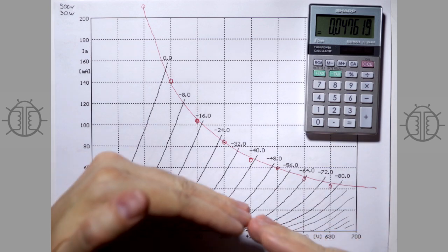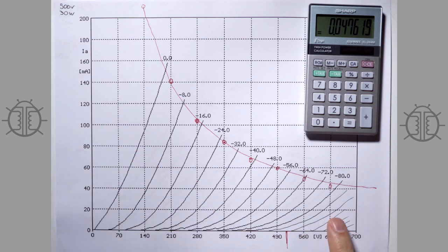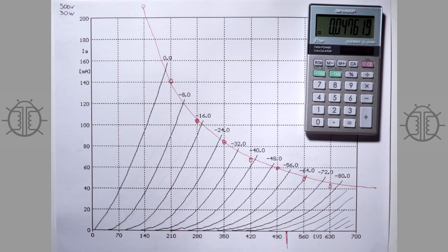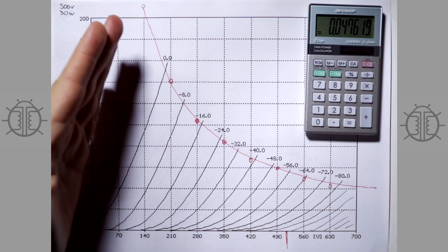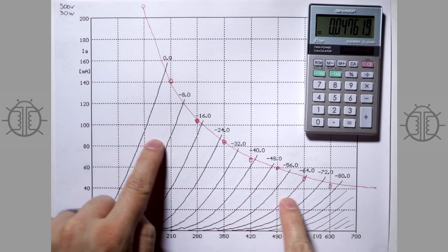So we want to be able to swing up and down fairly equally. It will soft clip up here as it reaches a maximum voltage, and it'll round off. And it'll hard clip down here when it gets to 0 volts, if your driver stage is not specifically designed to drive the grid positive. So we want our swing to be in here somewhere.